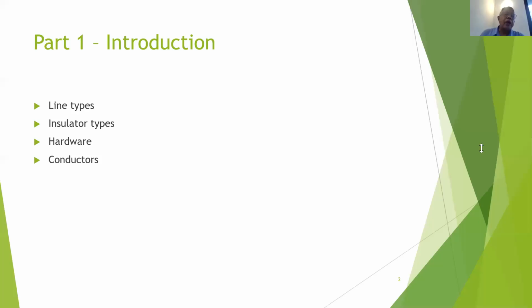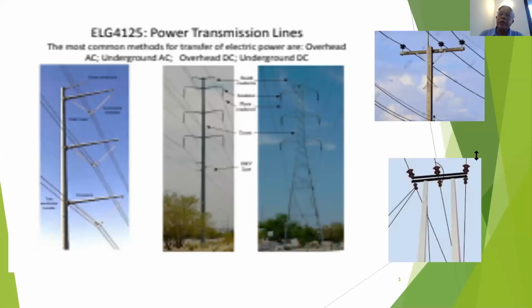Okay, now here on your right hand side, concrete poles, 33 kV lines, a suspension pole with pin insulators, and right at the bottom on the right hand side you have a tension point with a disc insulated string.